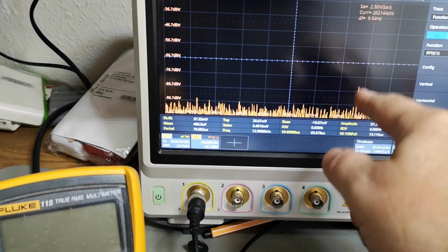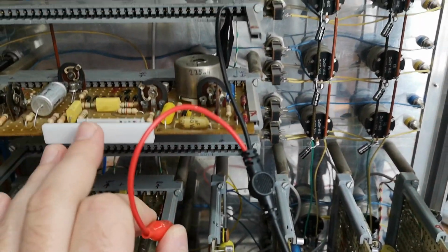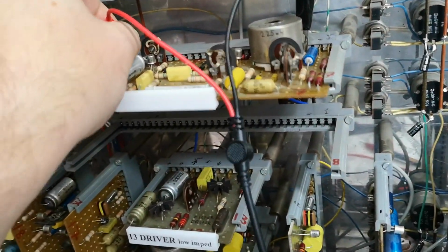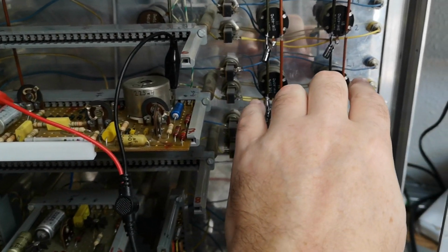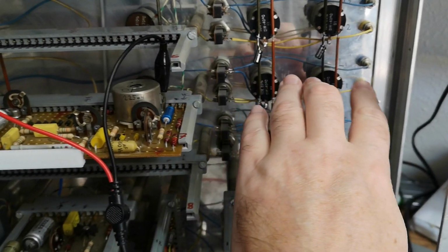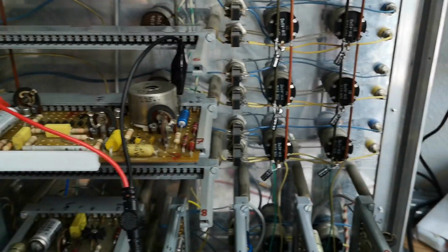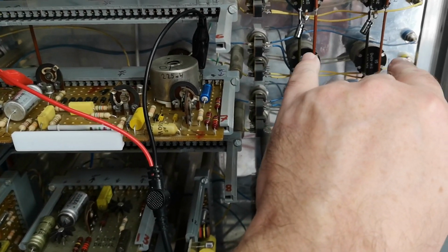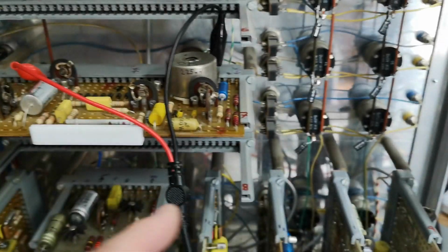And this is, of course, the modulator at 8 kilohertz. So let's try and only play with one filter. So now I'm looking at the output from that filter. And here I got the level and the frequency of this filter. So there's both of them, voltage inputs from the potmeters, voltage controlled, level and frequency.